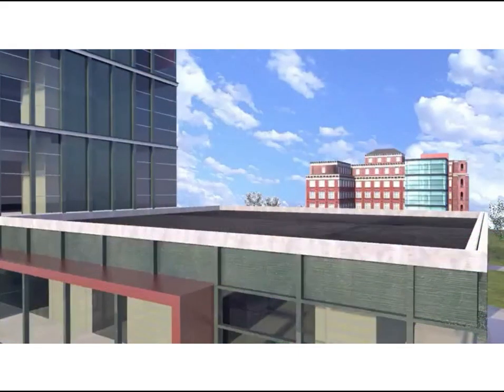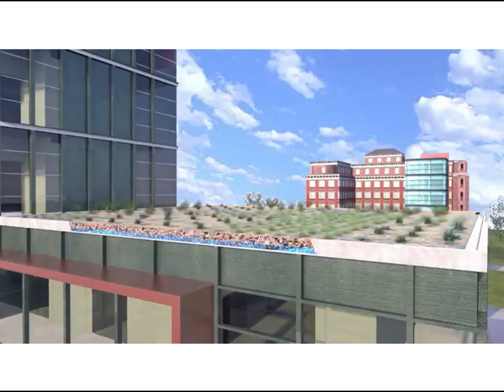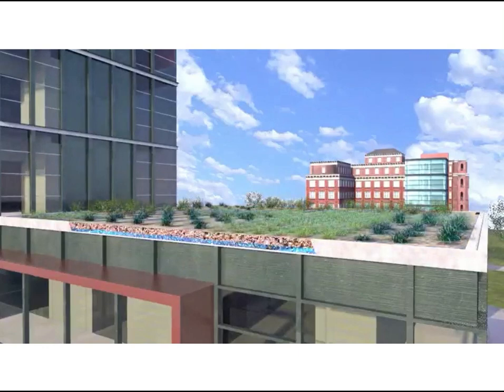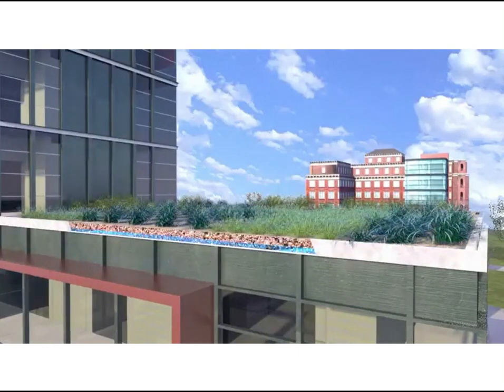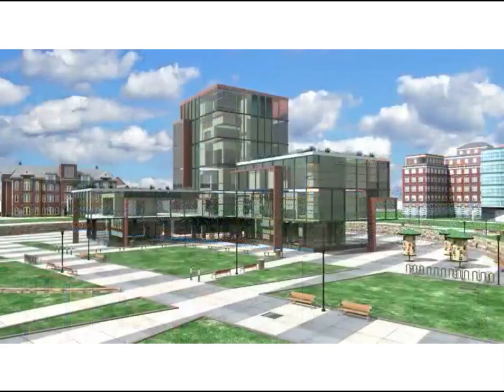The first system is a green roof placed on top of a building. The green roof is layered with drainage materials, compost or planting soils, and vegetation. The green roof can absorb some of the rainfall, reducing the amount of water flowing into the storm drains. Another system involves porous pavement.